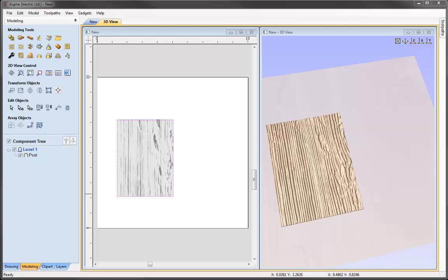There's definitely potential for using component images, but it's good to understand the limitations too. Depending on the quality of the image depends on the quality of the model that you'll get. Now if I import a JPEG, a bitmap, a GIF or a PNG, then that's only going to find 256 Z levels from the model. And so if I have a lot of shallow curves, then as I scale that up or down, we may actually see stepping on it.